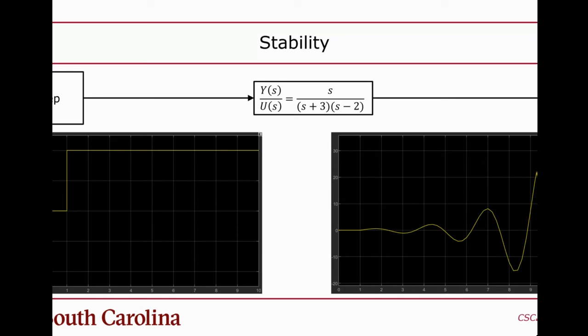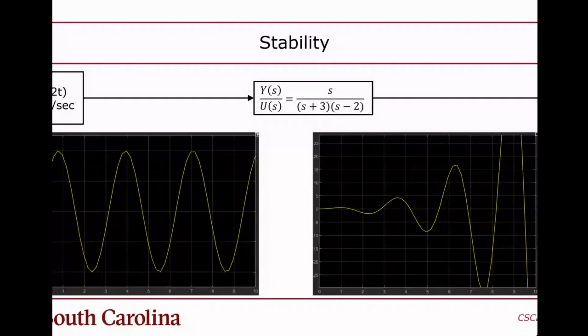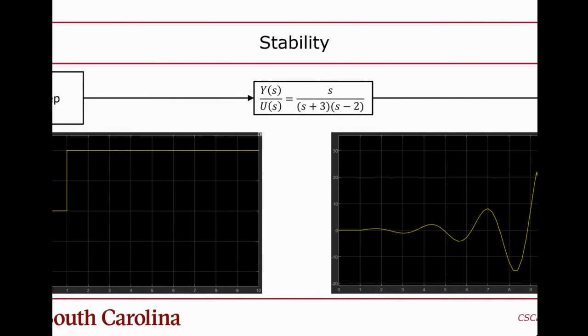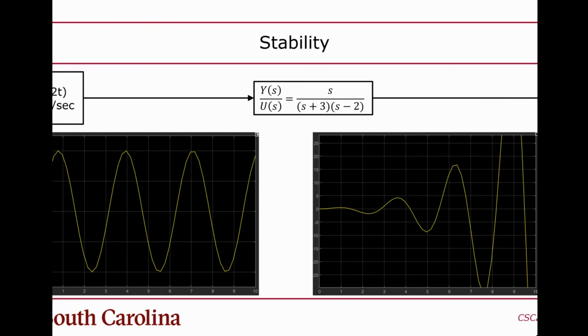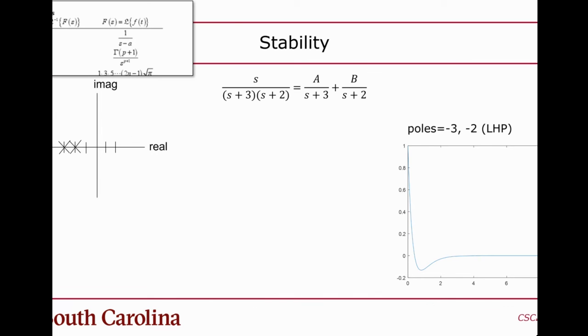But if you are interested in the step, this is an example of a step response. And again, I simulated this. I didn't do the inverse Laplace on this. This is strictly a simulation of the S domain. So you can see that, it's kind of weird. The step goes up, and then it results in this increasing ringing in the output that's unbounded. You can also do a sine wave response too, which you can see doesn't end well in this case. When I put a sine wave in, it kind of blows up on the output.